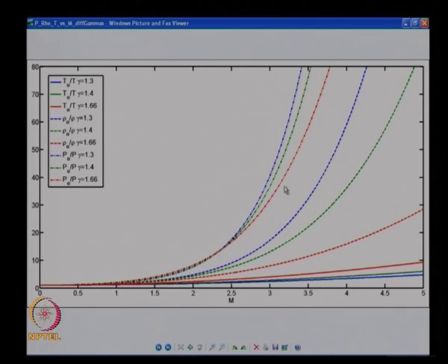When we look at the pressure plot, pressure drops very fast, in fact it drops the fastest out of p, rho and T, and the most compressible gas has the most change in pressure for a given Mach number. Most compressible gas gets maximum change in pressure when we are accelerating to a particular Mach number.